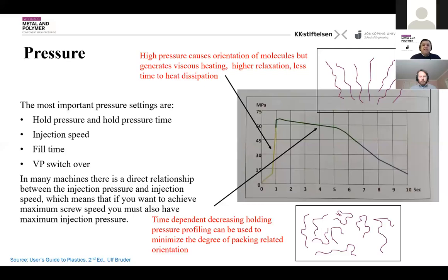The answer is that as soon as the liquid polymer is injected into the mold, the molecules attain directionality parallel to the applied pressure. So now we have molecules oriented parallel to the applied pressure, whereas the underneath soft polymer still has the molecules in the coiled form, which is their natural tendency.